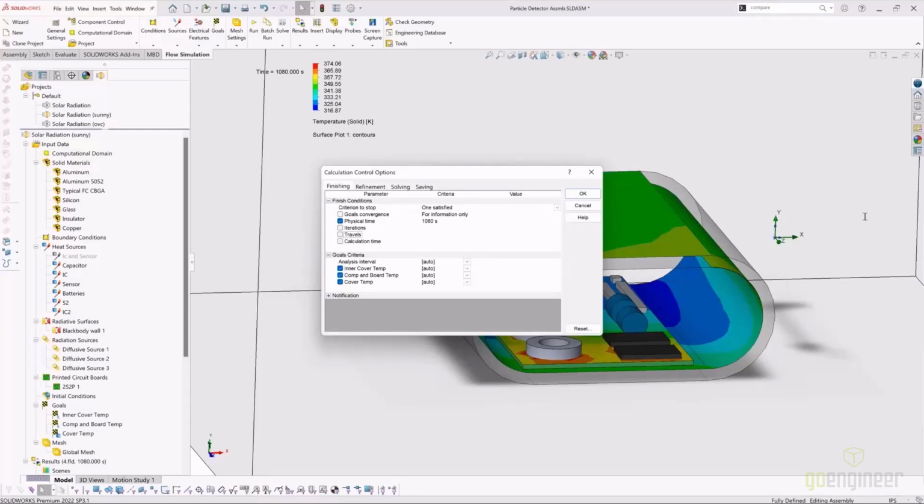And travels is just how long it took for one particle to get to your start point, hit your end point, and go back to your start point. So how many times does your study reset the calculation? You could cut this off and say, yeah, I just want 2 travels. 4 is recommended for confidence and for getting the least amount of errors in your